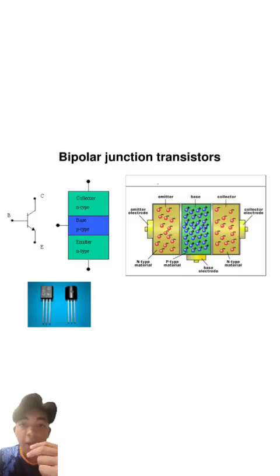Okay, bipolar junction transistors (BJT) are made using semiconductor materials, which are essential for controlling the flow of electric current. The most common materials used in BJT are silicon, also known as Si, and germanium, also known as Ge. In the early days of transistor development, germanium was widely used because it allows current to flow easily due to its high electron mobility.